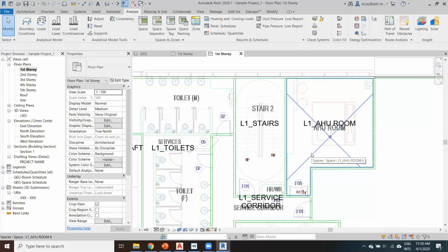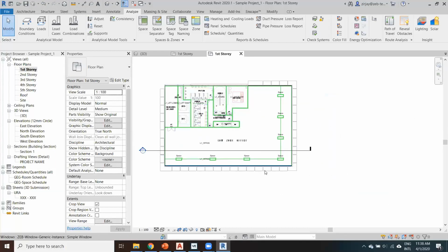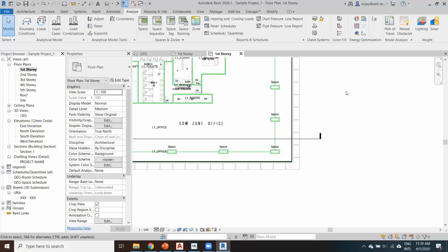And there are limits to IES. It cannot follow too complex shapes. If we have plans that are round, that have a round profile, what we do is we try to facet it. I mean, create several straight lines. Try to stay as close as possible to the arc of the circle, but without actually being an actual circle.